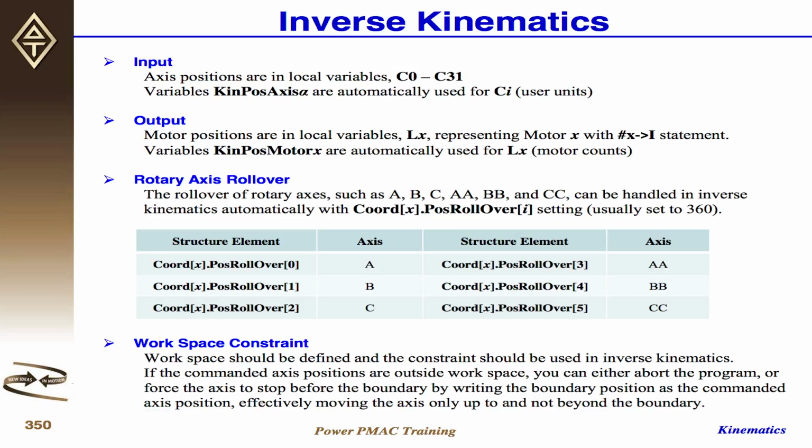Okay? There are some other axes. In all the 32 axes that we have in one coordinate system, we have the linear axis and the rotary axis. Rotary axes are these: ABC and AABBCC. The linear axes still have two groups. One is the Cartesian axes: XYZ, XXYYZZ, UVW, UUVVWW. So we have four different sets of Cartesian coordinate systems. For the rotary, you have these two.